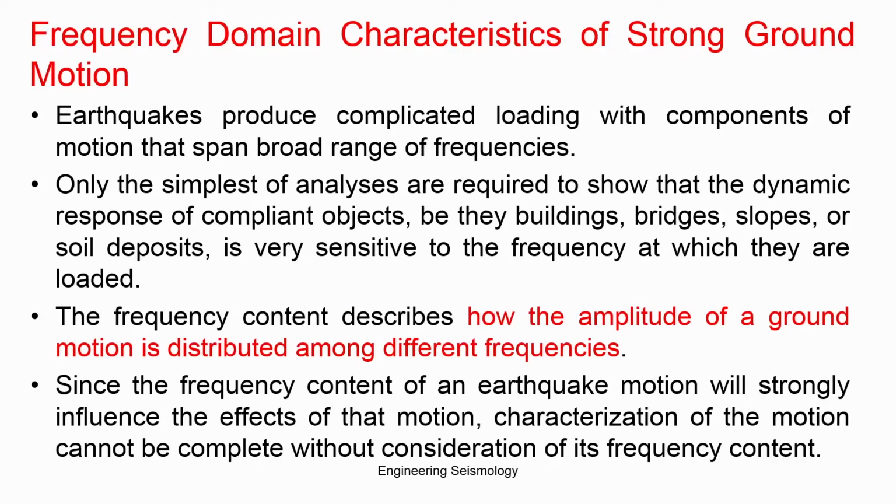The earthquake produces complicated loading, with components of motion that span a broad range of frequencies. Only the simplest analyses are required to show the dynamic response of objects such as buildings, bridges, slopes or soil deposits, which are very sensitive to the frequency at which they are loaded. Different structures have their own natural frequency.